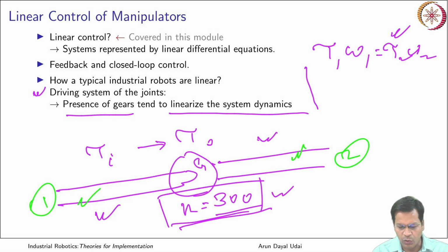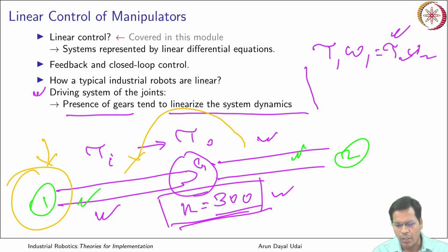And even the joint which is driving this link can also be handled independently. You need not worry what torque this link is going to transfer. So basically both are isolated. They can be treated like an isolated link. You need not worry what kind of effect this link is going to have on this link. So they are decoupled that way.